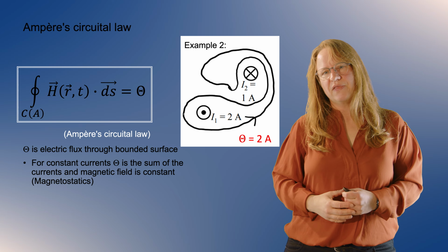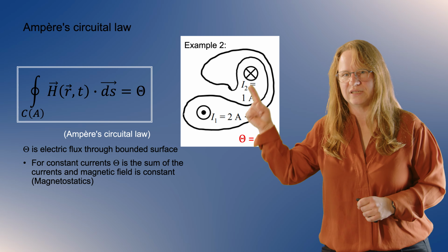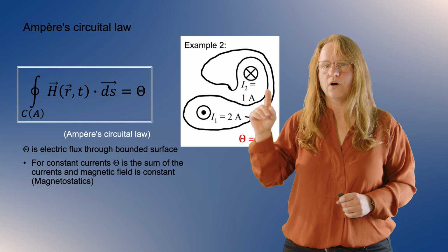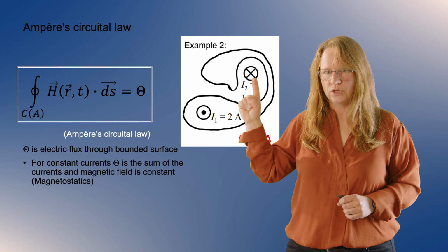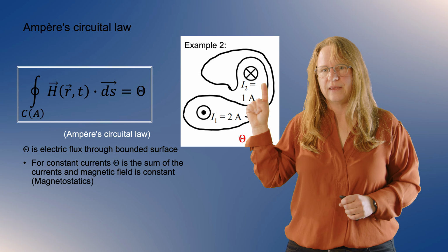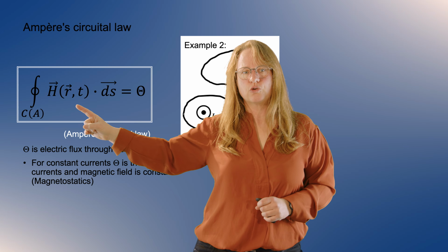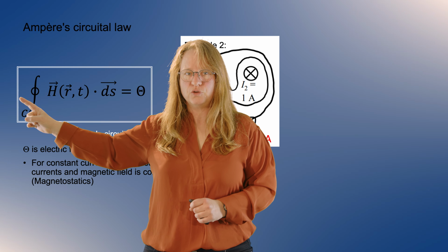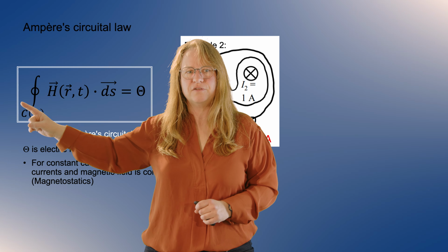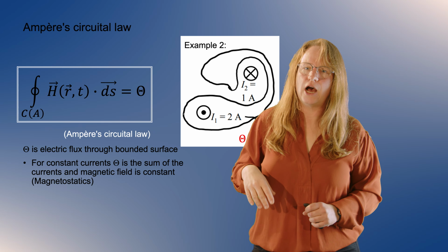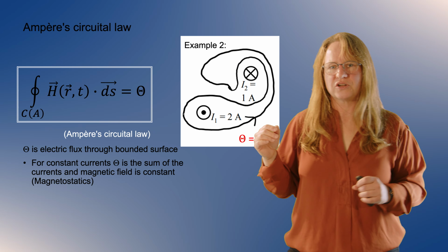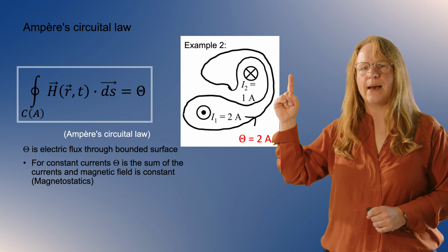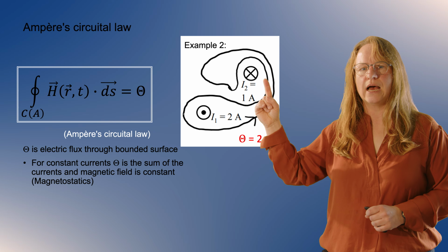You might now say, well, that is a bit strange because the current is there, and it should generate a magnetic field also. That is completely true. Of course, this current also generates a magnetic field. What Ampere's circuital law is talking about is the integrated magnetic field if you integrate along the contour. And how you can resolve this paradox, as it seems, is by considering that the contour is going up here on one side and going down on the other side.